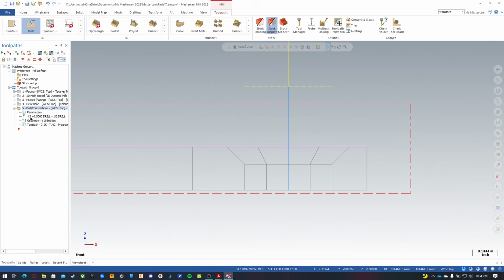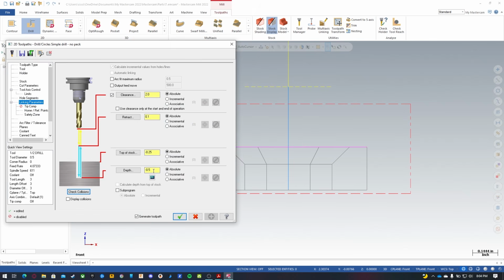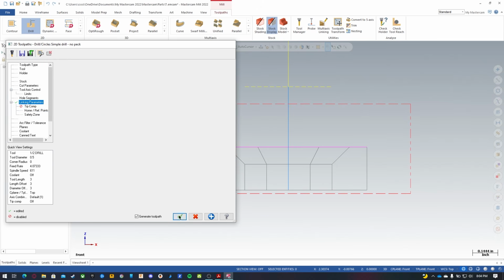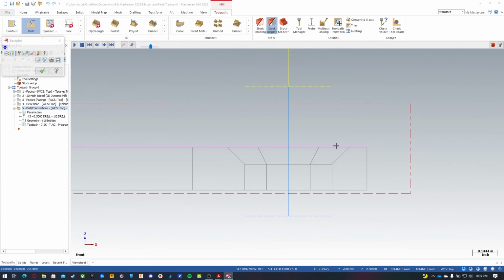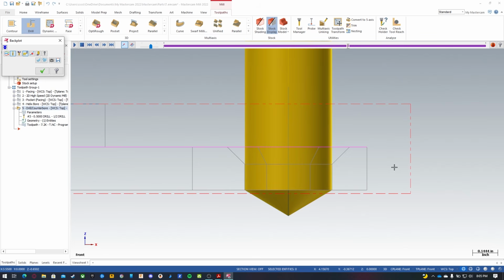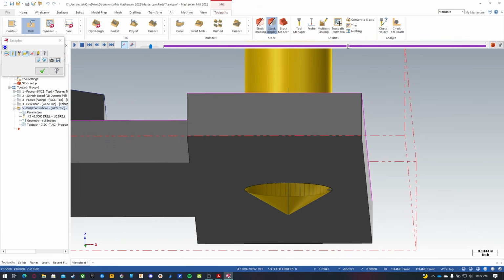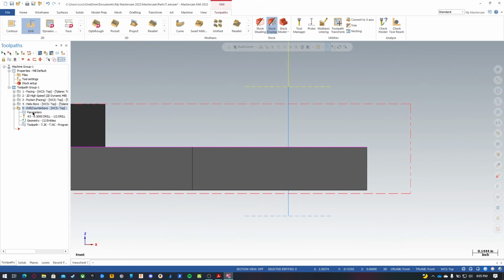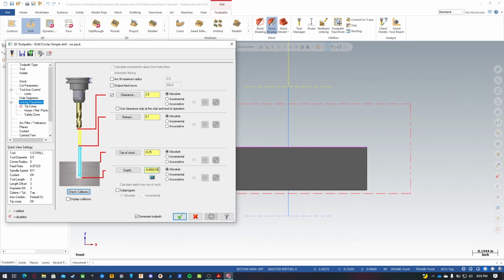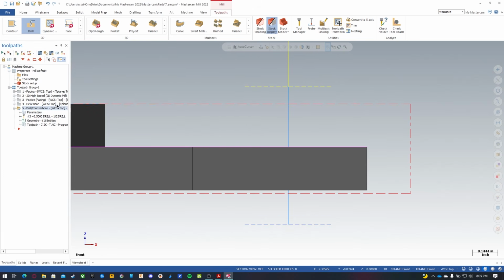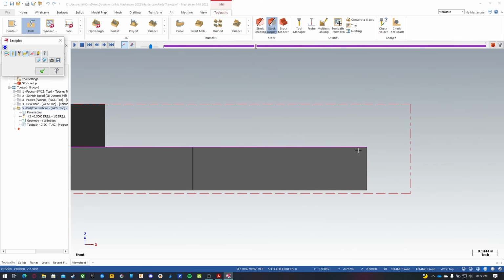That's not far enough. Whereas if I put just my drill point, this still isn't quite enough. So we might get a little burr that kicks out from here. So that's why we throw on an extra 50 thou or so. So that 0.700, click OK, and now we have that.